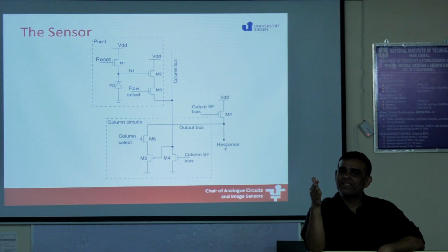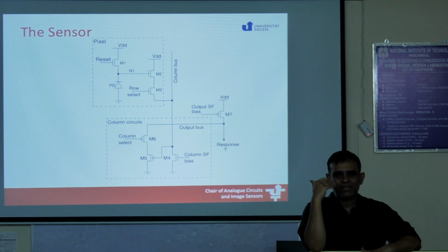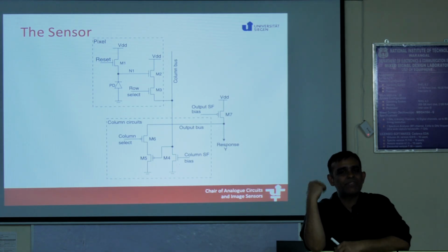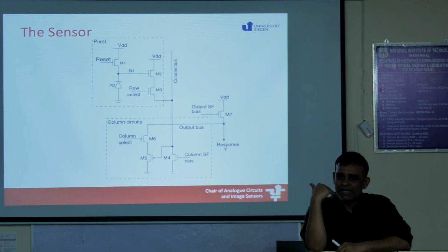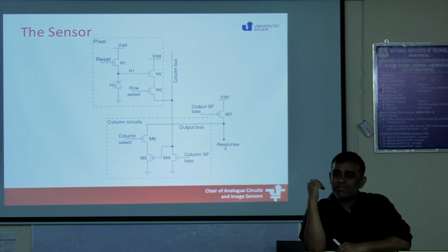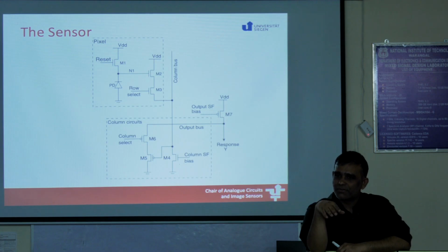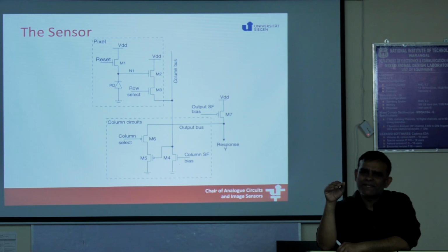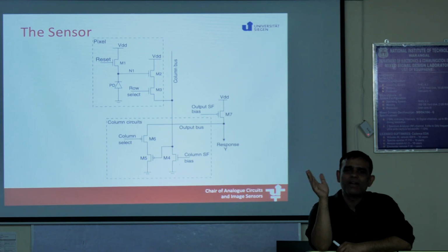So today we finished at the active pixel sensor. This is called an APS, active pixel sensor. In more advanced technology, we will have a 4 transistor active pixel sensor, and that is to remove noise. We have already seen our image is noisy. So we would not like to remove noise in the software domain, because if it has gone all the way till there, we have already lost quite a lot of signal. So we like to remove the noise using circuit approaches right at the pixel level. But for all practical purposes, the 3 transistor pixel will work.